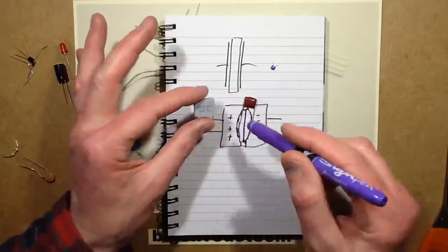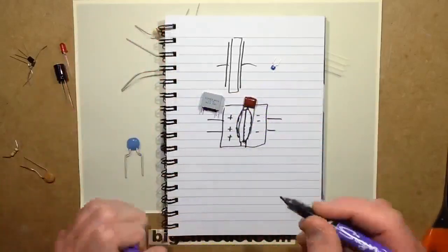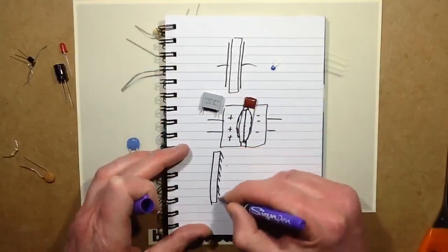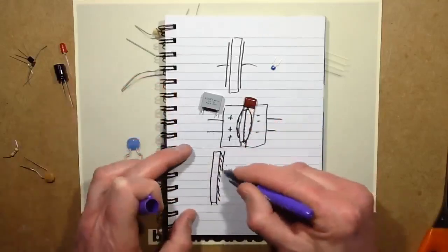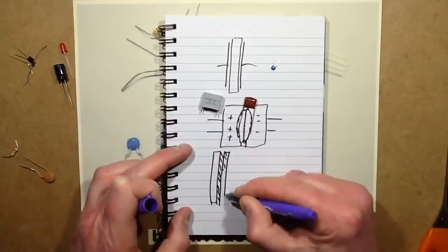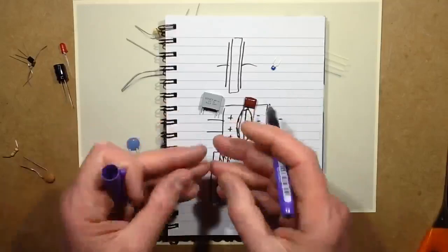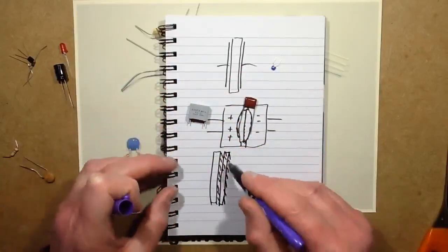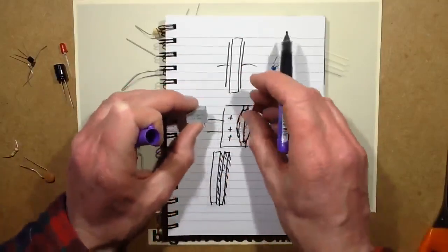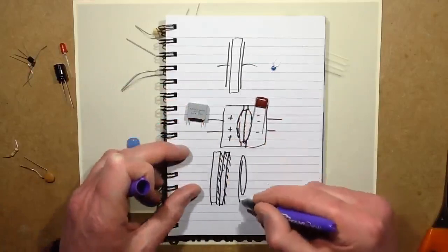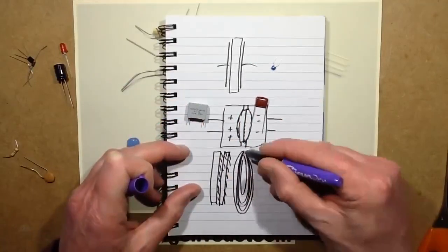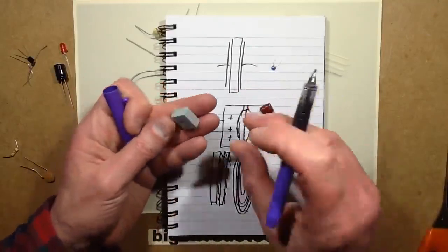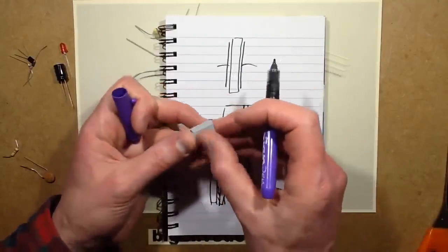And to make this type of capacitor, these are metallized film capacitors, and it's a film that's metallized on one side. They take two strips of it, and they basically sandwich them together. The plastic aspect of it is the insulator, and the metallization is the electrode. And to fit a lot in a small area, they then actually just spiral. They take a big long strip and they spiral it round into a small area, and that's what creates the sort of larger area. And the thickness of the plastic film itself will determine the voltage rating.